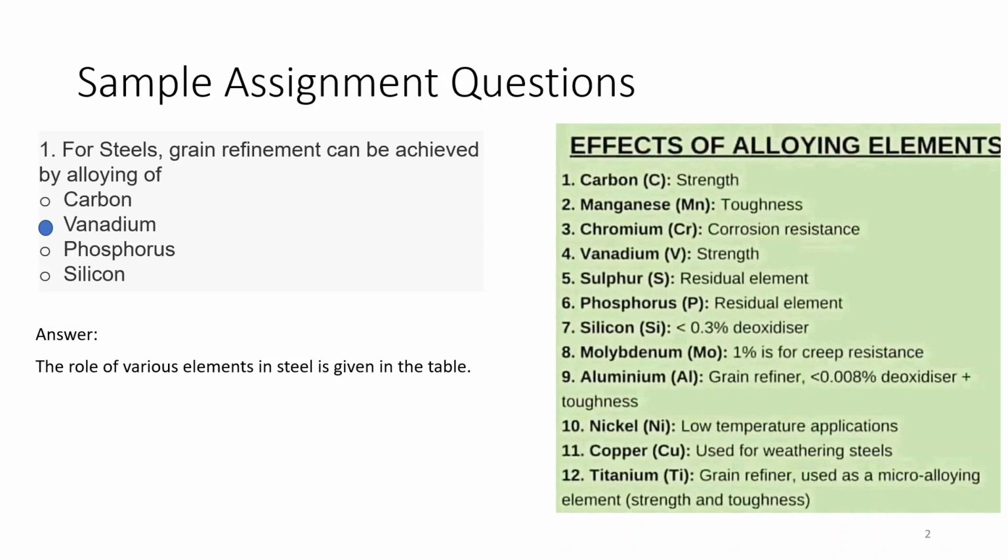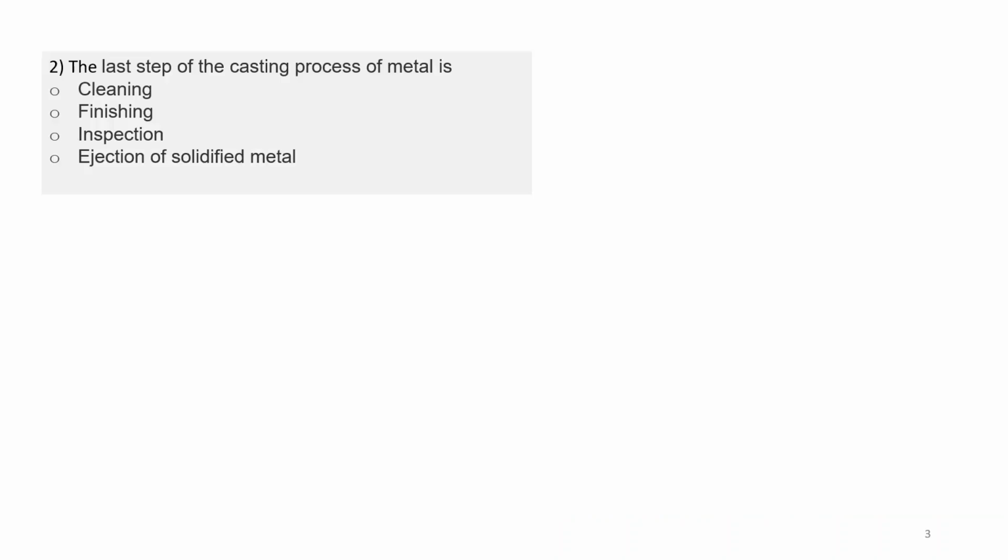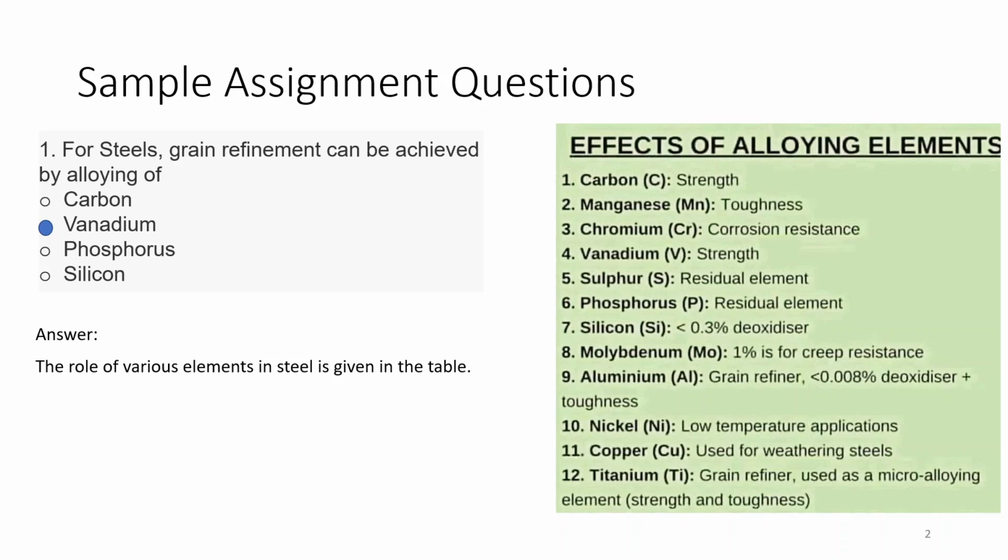So as I told earlier, by reducing the grain size, there will be a Hall-Petch type of equation that you read earlier, so that will be helpful here. And other elements, sulfur and phosphorus, act as impurities in steel.